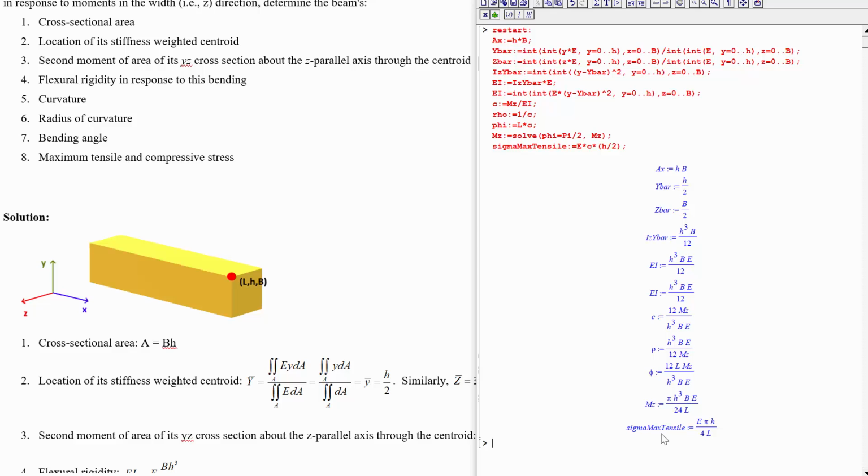And that tells you that the maximum stress that you're going to get it to bend to 90 degrees is the Young's modulus. So higher Young's modulus is going to need more stress. Pi by 4, so just a geometry value there. And then the thickness divided by the length. So the longer the length, the less stress it's going to take for this to bend to 90 degrees. That kind of makes sense because the same stress, the same moment, will cause this to bend more of an angle if the thing is just longer, right? And it's proportional to the thickness.